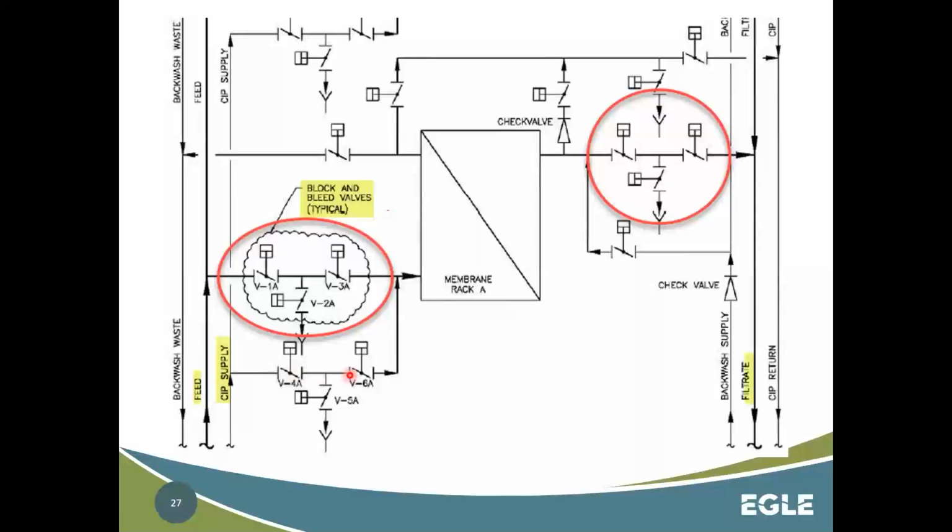rather than those cleaning chemicals now being right up against this valve, which could also fail, it would just drain out through this open drain valve. And so that should normally be kept open. And if operators notice that it's dripping chemicals or dripping water from this side, then they would know one of those valves needs to be replaced.